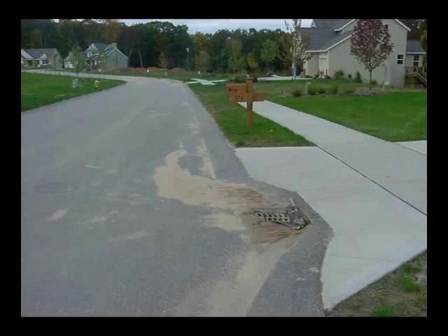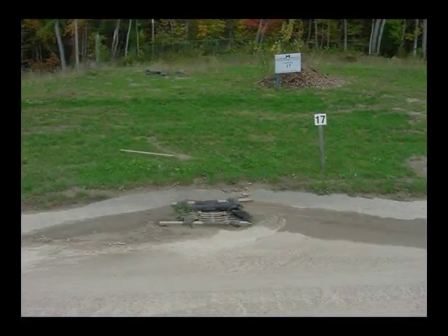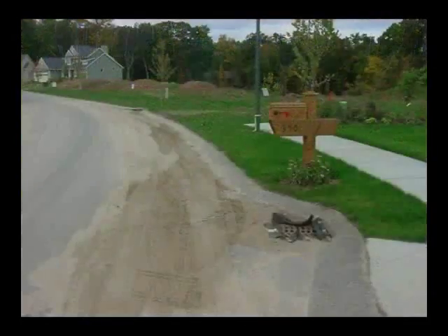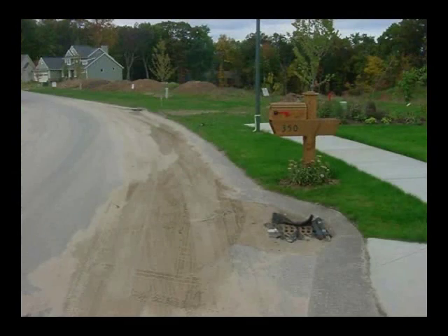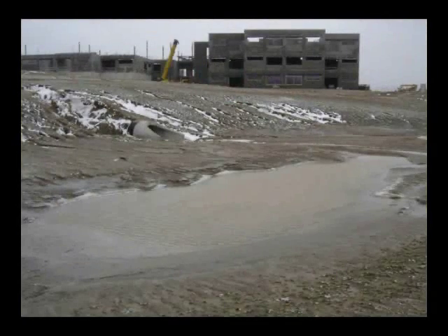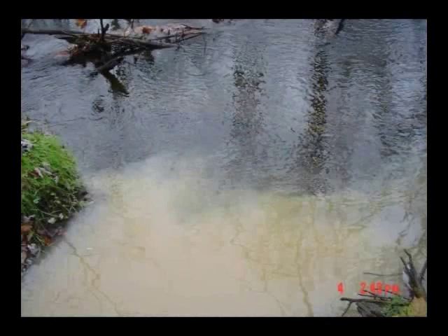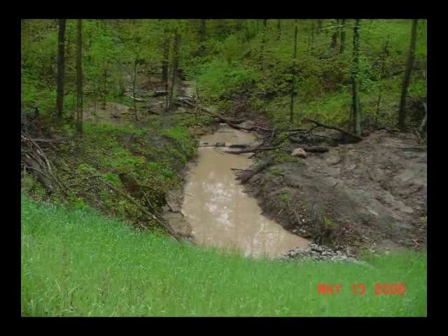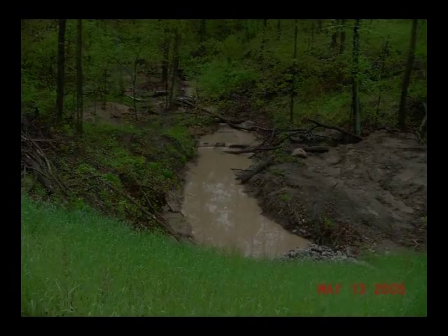Storm sewer inlet protection is a sediment control. Storm sewers are often direct conveyances of stormwater to surface waters. During construction, all storm drain inlets must be protected from sediment inputs in order to prevent storm sewer clogging, over-sedimentation of detention basins, and to protect lakes, streams, and wetlands from direct discharges of sediment and other construction-related pollutants.